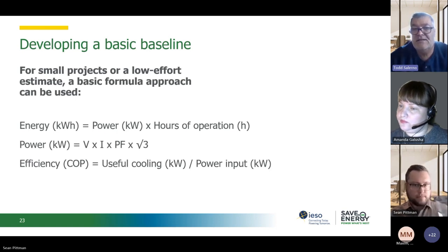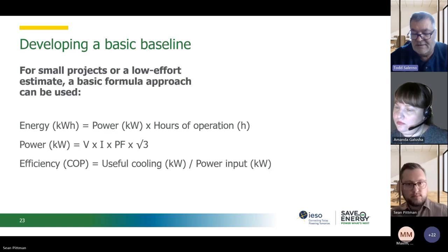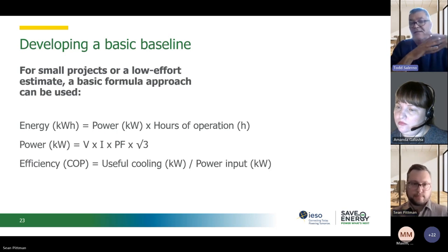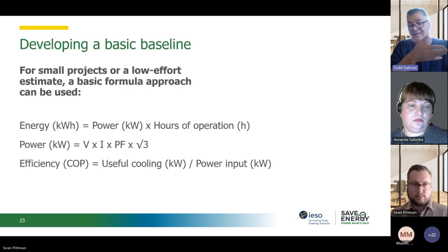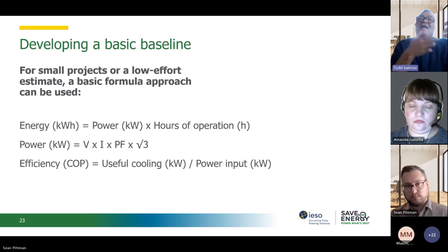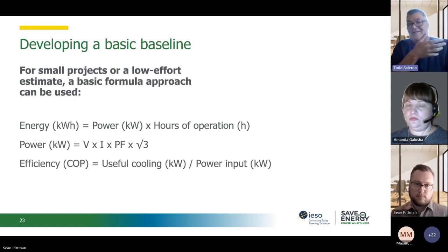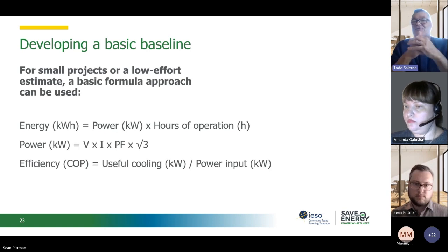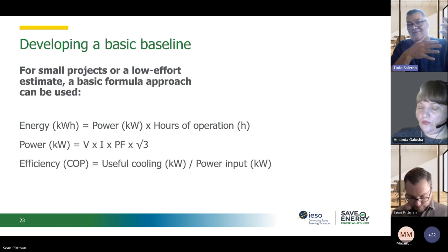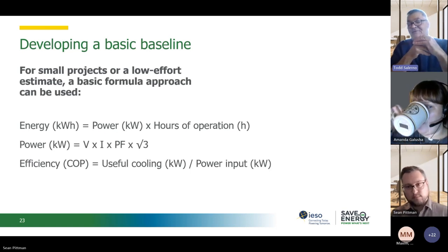Yeah. There is published data for most, especially for centrifugal chiller systems and newer systems, there's the integrated part load value, or IPLV, where you can get what the kilowatts per ton or COP is at the different loads. Now, when you're doing a baseline, you might have to resort to published data, but the actual chiller system that's in place, and it might have been there for 15 or 20 years, might not be performing at that level.